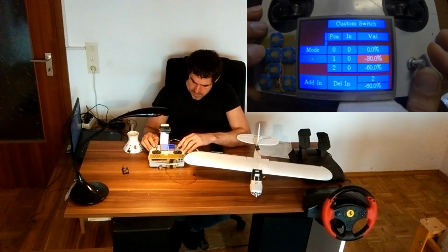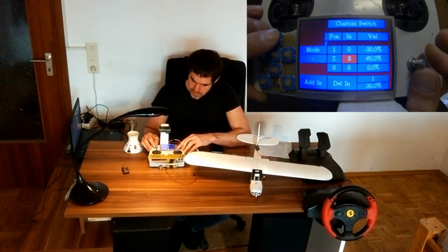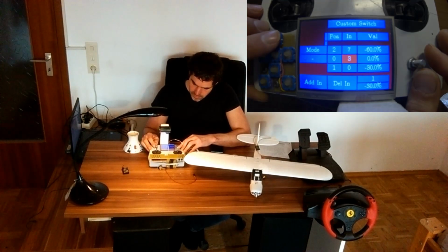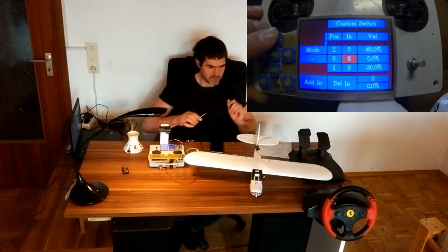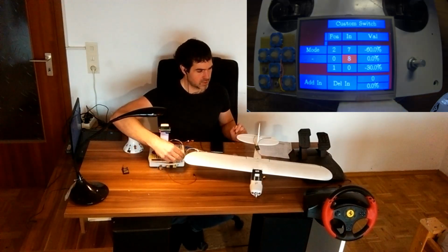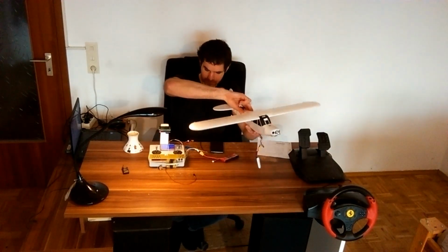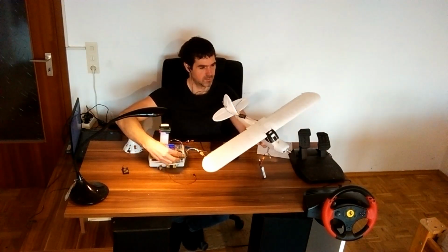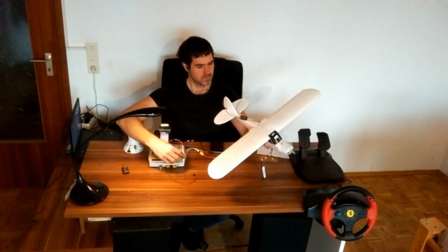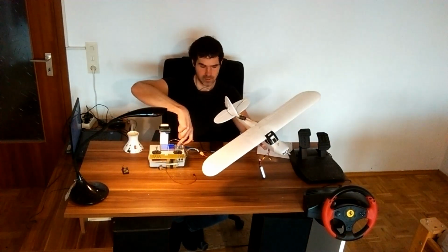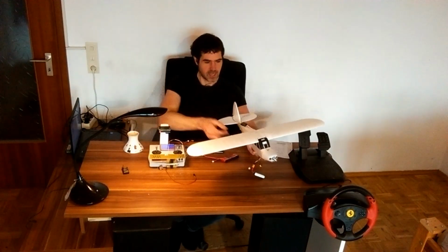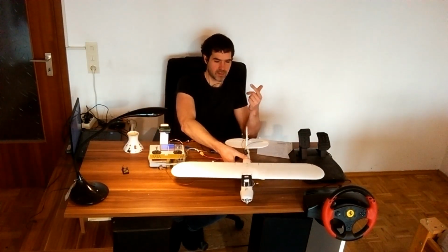So now I forgot to set the inputs. This stays neutral. The 2 will be 7 and 0 will be 8. So now when I use this switch, I have the Flaperon functionality. And I have the flaps already. Okay, I'm going to save this because I'm coming back to that later when I'm going to give the demonstration